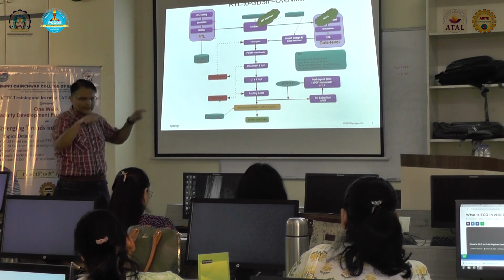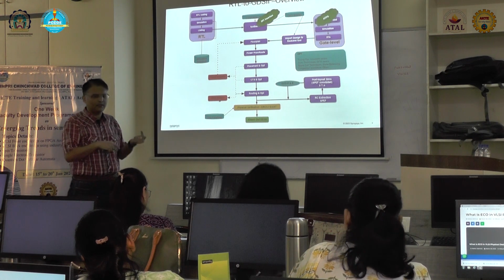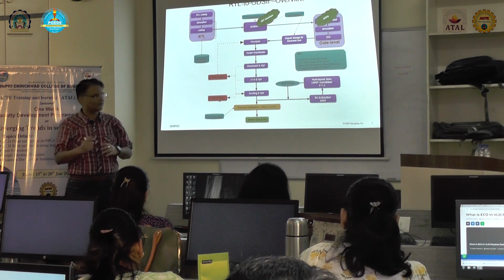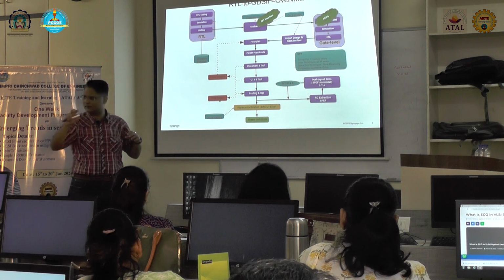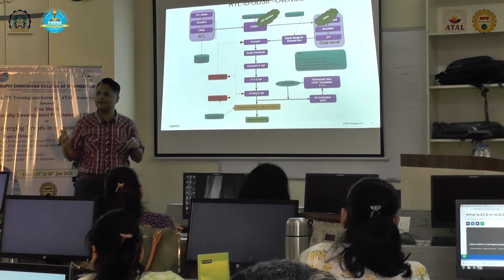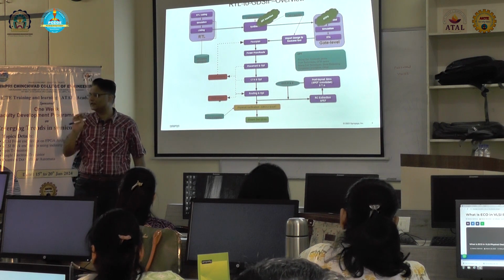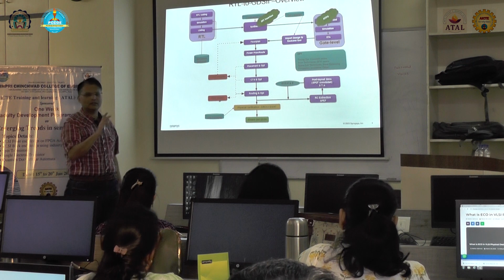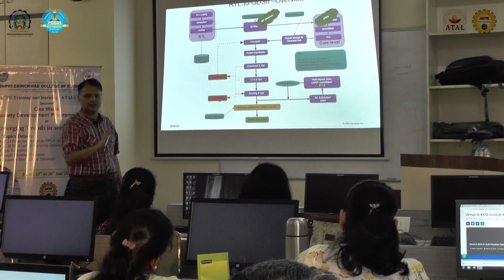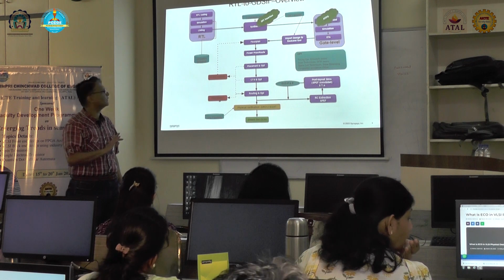Okay. So we will create some scan chains inside the chip, and we will shift the pattern in, and we will shift it out. There is a shift register created using all the registers. The idea is not to verify the functionality of the design, but to verify whether the flip-flop is working correctly, whether the NOT gate is working correctly, things at a very low level. It is not the functionality of the chip. But if a flip-flop is there, does it store, does it work correctly? If it's a NOT gate, does it work correctly? That is the intention of DFT.